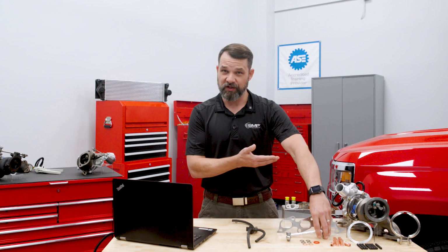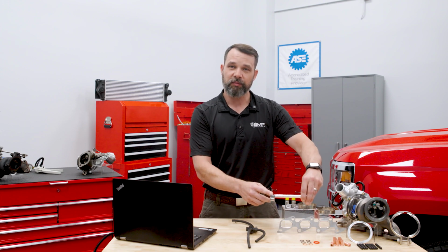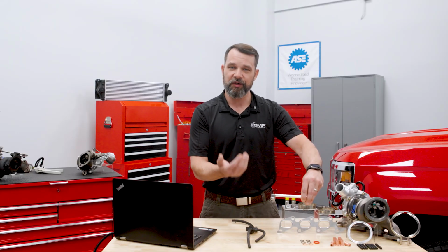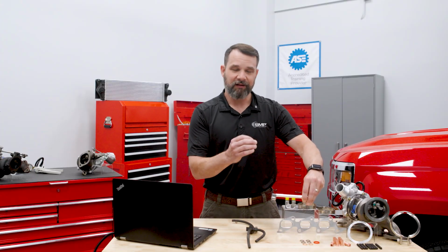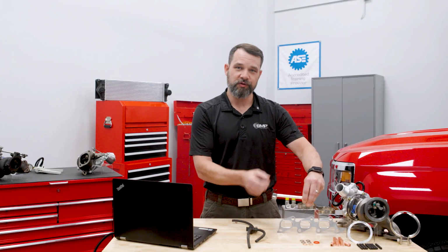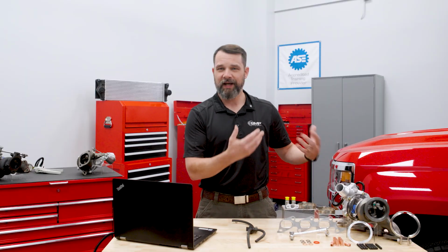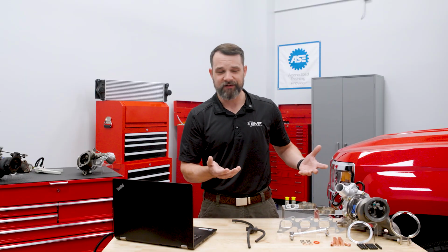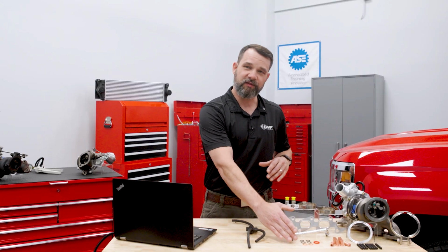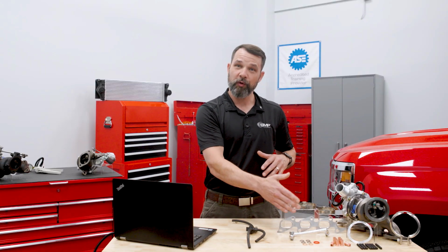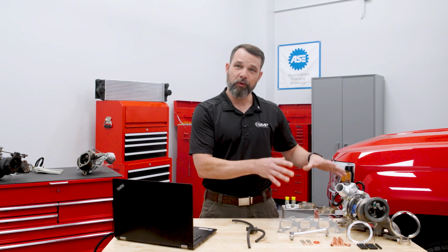Things like on this Chevrolet Cruze, I'm sure you've done any of these turbochargers before, you know the supply line for the oil to the turbocharger had a known issue, and that was that it was easily clogged. This is the updated design, and the last thing we want to do is replace a turbocharger, put that old design back on, and end up starving the new turbocharger after the repair is done. Doesn't make any sense. So whenever we do get a kit, make sure we use everything in there. We're going to be sealed properly, we're going to have proper oil supply to the turbo, and everything's going to mount up the way that it should. So that's just one point to make here.